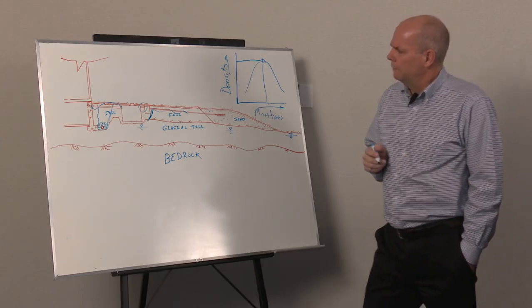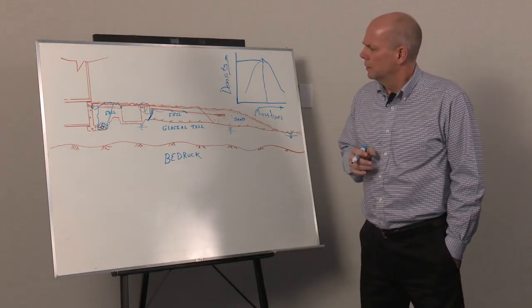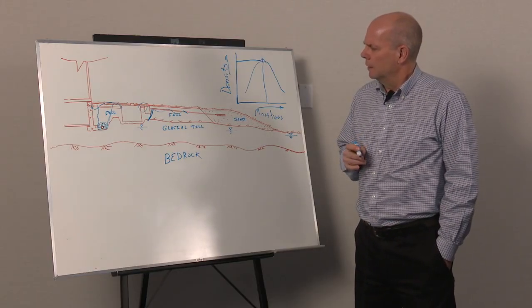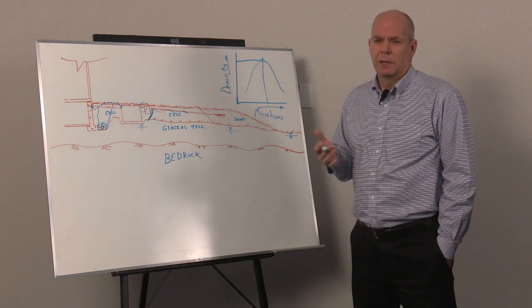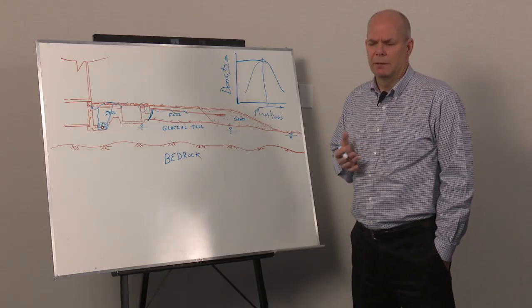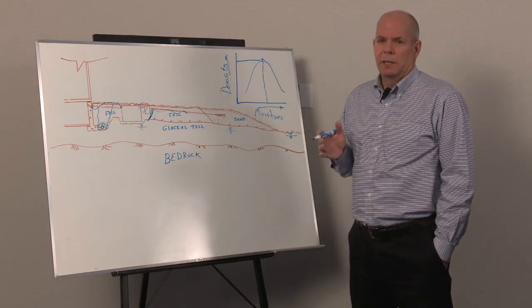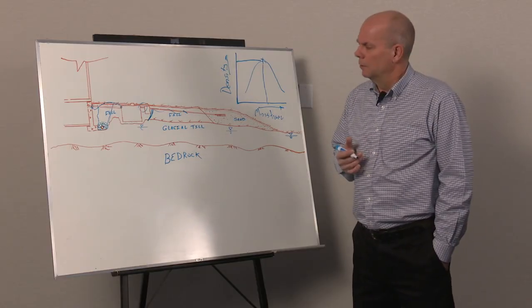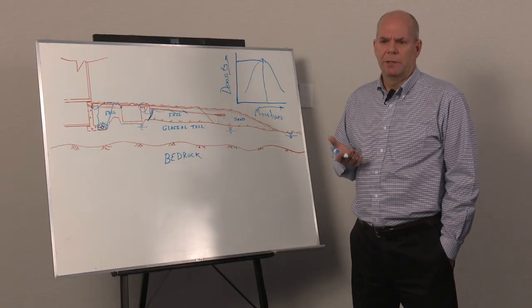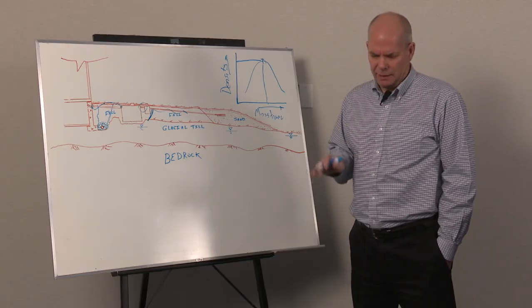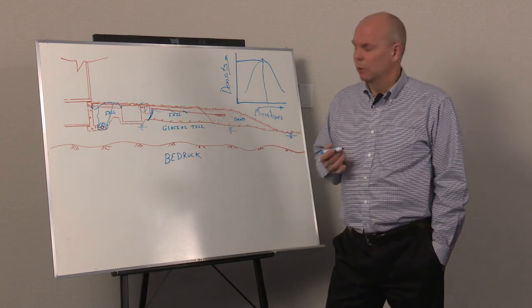So when placing fill, there's different pieces of equipment that you can use to place it and compact it. The equipment that's typically used would consist of, say, a jumping jack, which would be the low-end piece of gear that's often used around some of this type of construction. I really don't like the use of that. That doesn't do much for real compaction. Compaction of these soils typically requires weight and vibration, and the vibration is not at the frequency that the jumping jack is working at. It's at about 1,500 cycles per second in that neighborhood.